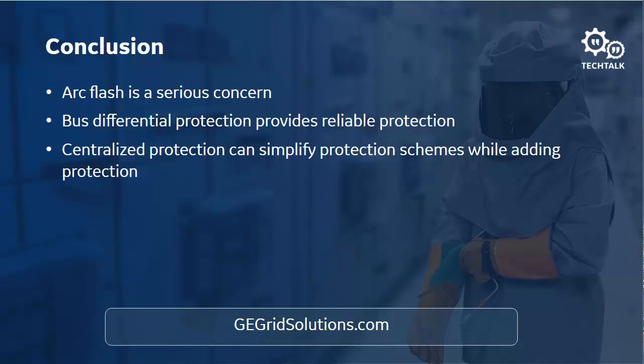So this question says, typically an arc flash relay is located at the switchgear cabinet. Do you recommend having a separate device/relay for the traditional protection elements located away from the switchgear? So for an arc flash relay, you need to have the sensor near where the arc flash is going to occur, so in the cubicle. Typically with the arc flash relays, it's a light sensor and it's on the relay that's protecting that element. So it is in that same cubicle.